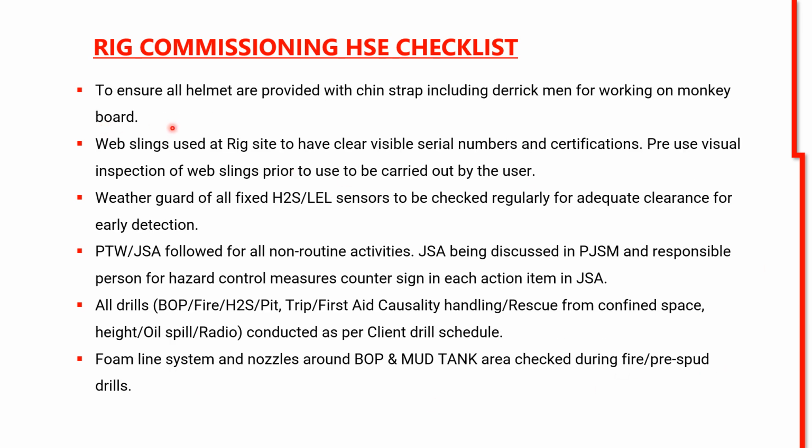To ensure all helmets are provided with the chin strap, including the derrick man for working on the monkey boat. Web slings used at the rig site to have clear visible serial numbers and certifications. Pre-use visual inspection of the web slings prior to use to be carried out by the user. Weather guard of all fixed H2S (hydrogen sulfide) and LEL (lower explosive limit) sensors to be checked regularly for adequate clearance